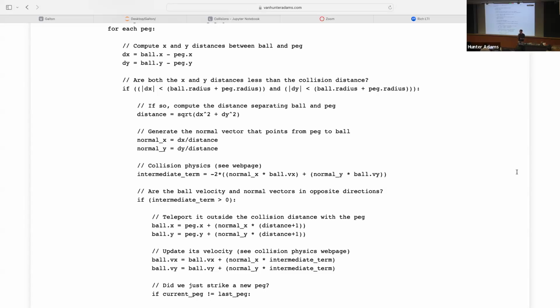The flight computer was actually smart enough to recognize that's an error. And so flight computer A said, oh, I've got an error. Let me pop over to flight computer B. Flight computer B, of course, had the same error because it was running exactly the same software. So flight computer A rebooted, and it was programmed such that on reboot, it would print out some diagnostic information, as many of our programs often do. In flight, that diagnostic information was interpreted by the flight computer as the horizontal velocity of the rocket. The flight computer went, oh my God, I'm going the wrong way, and gimbaled the engines really hard, so the rocket turned in air and the aerodynamic forces blew it up.